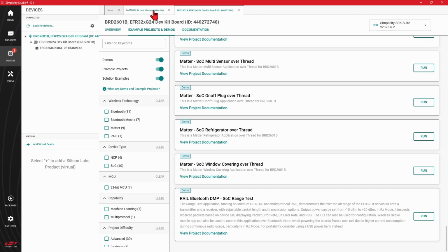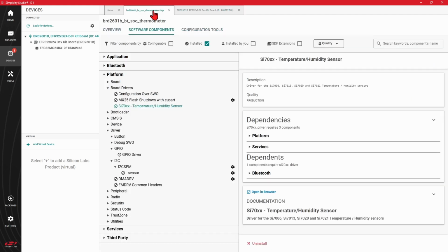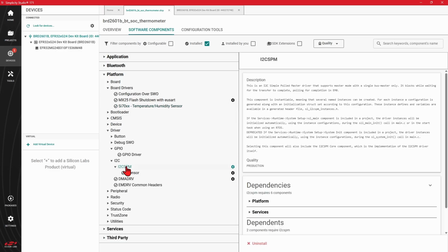Similarly, once you have your starting project, look for components to help you at the highest level possible by using the search box. If you need to add a temperature sensor, search for one. Only drop to a lower level, say I2C, and write your own driver if you don't find the sensor you need.